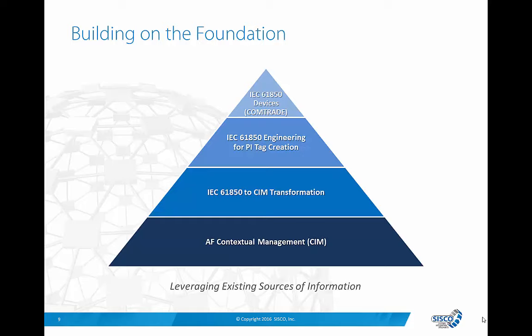Once you deal with CIM in the electrical environment, there is another standard, IEC 61850, that is becoming more and more prevalent in substations and in industrial complexes. Obviously, if the information exists in 61850, we want to be able to translate it into CIM and bring that information into AF. Going even further, 61850 engineering processes can enable automatic PI tag creation and PI interface configuration.